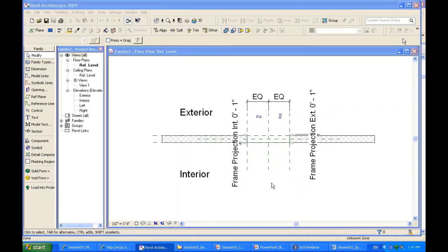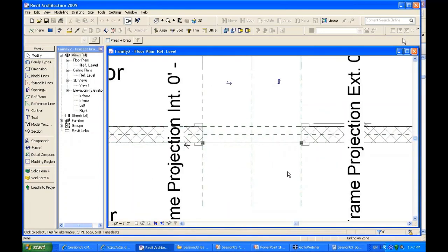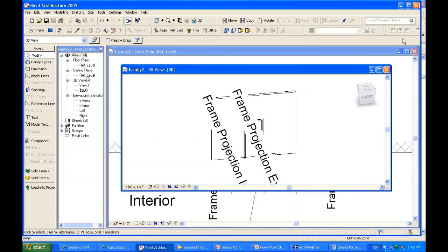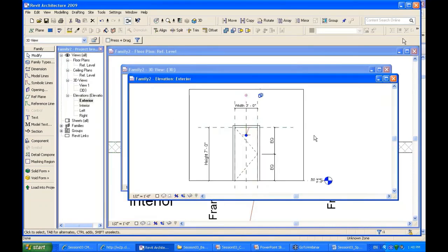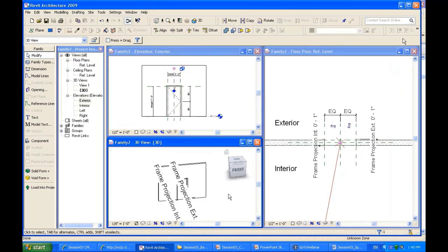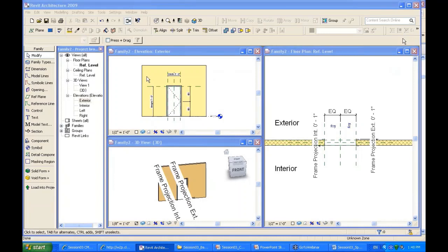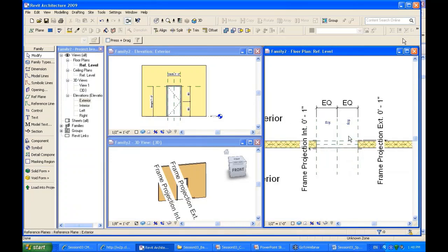And it's giving me some content. And if I look in 3D, it's got some other things. If I look in an elevation view, it's got some other things. I'm going to window tile and turn shading with edges on all. Shortcut, SD, shading with edges, just so you can see. And what do we see? We've got stuff we don't need, because we need a CMU door.